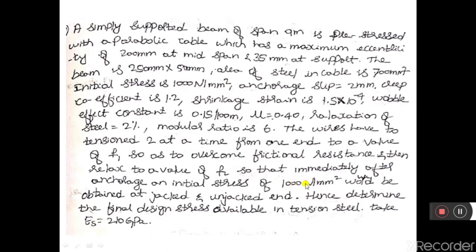That is one condition. It is also given that F1 is applied so as to overcome the frictional resistance and then relaxed to a value of F2 so that immediately after anchorage an initial stress of 1000 Newton per mm square could be obtained at the jacked and unjacked end.